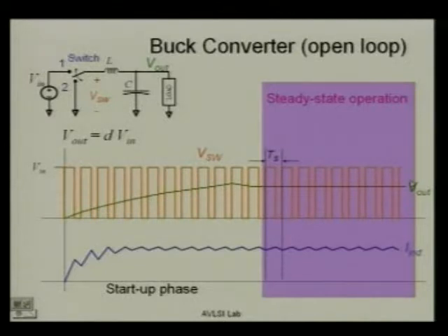This capacitor needs to be charged up to that voltage, the inductor needs to be charged up to that current, and these will charge and discharge, and slowly it will reach a periodic operation. So this thing is called the dynamics. There is a certain dynamics involved in the behavior of the converter. Similarly, say we will talk of load transient.